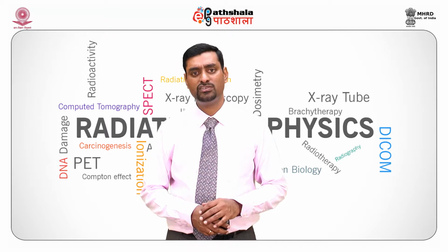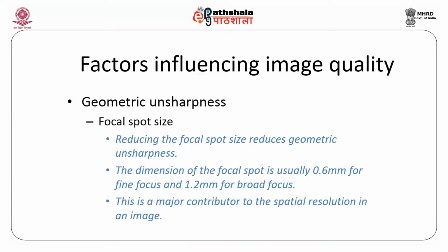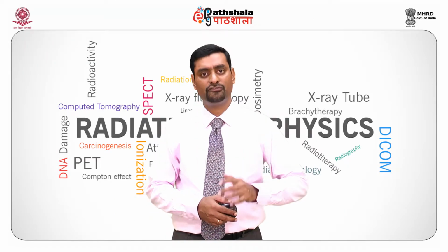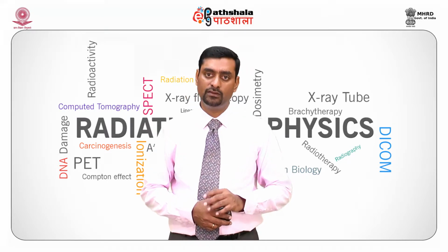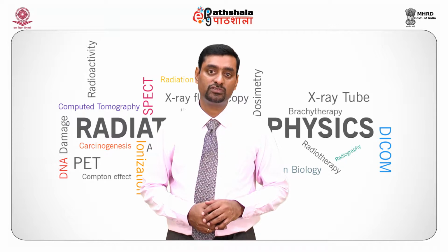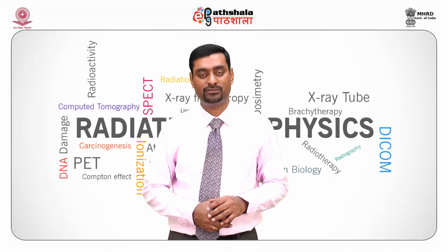Next, we move on to geometric unsharpness, which also influences image quality. There are lots of subdivisions in geometric unsharpness. Focal spot size. By reducing the focal spot size, it reduces geometric unsharpness. Consider fine focus, which is used in X-ray machines. In an X-ray tube, when fine focus is used, the image resolution is much better compared to the broad focus.